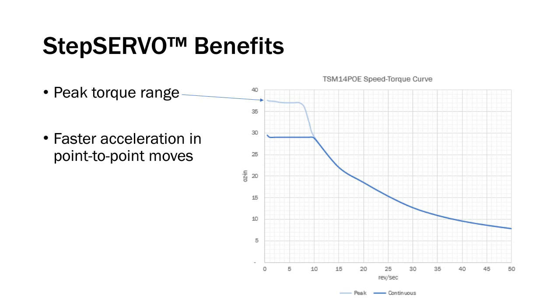step servo motor. And in this particular example, we get that peak torque up to almost 600 RPM. I mean, this speed torque curve shows the motor going out to 3,000 RPM. Sure, it has a little torque out there, but most stepper applications are under 1,500 RPM.